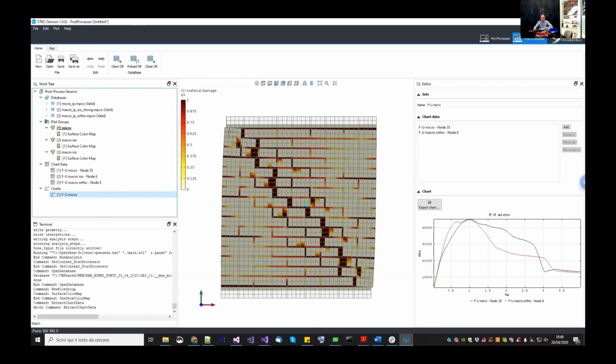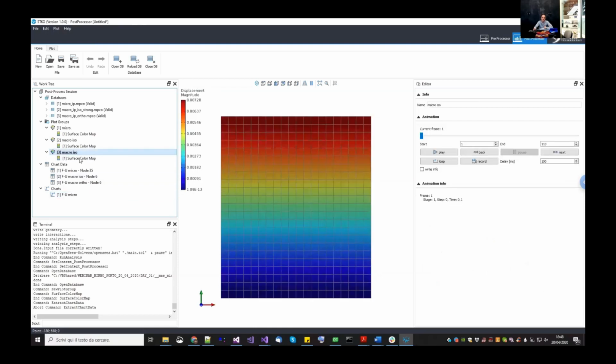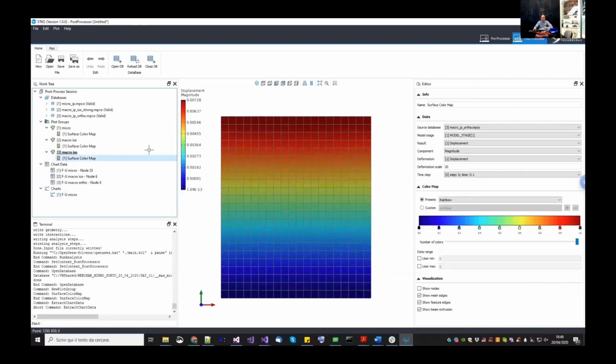When the micromodel is trying to break into this line, which overall is a diagonal line, it is actually not like that. So you see a combination of tensile crack in the bricks, sliding in the mortar joint, and only tensile failure in the head joints here. And of course, the path is not linear, so it takes some time for the crack to reach the two different toes. Okay. Well, when you see the same thing in the macroscopic model, it is completely different.